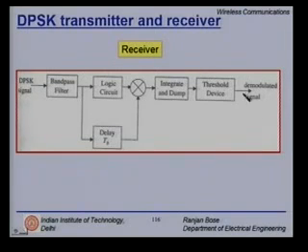Fairly simple. This is the added advantage why DPSK is popular. Very simple design, and you do not have to recover the phase because it is simply differentially encoded. Of course, it comes with a price. There is about a 3 dB loss in performance.